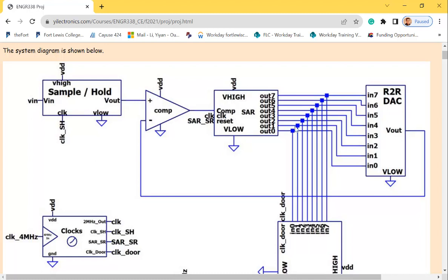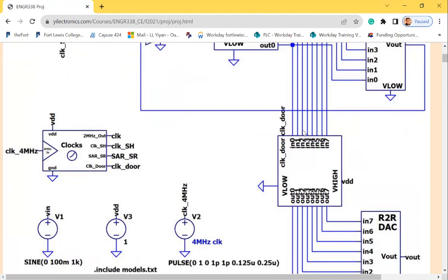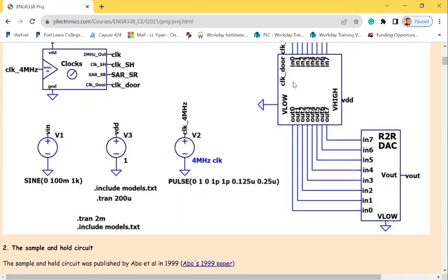the output over here is already a digital signal because this is an ADC. I need a digital signal as an output, right? So the analog input with the digital output. However, these 8 lines have all the values, including the intermediate values. Remember all the circles in the middle? So it has all the values in the middle. So I do need a register whenever it's ready. Okay, I can sense it and trigger the D flip-flops and send the correct output over here. So this is just an array of D flip-flops, nothing else.